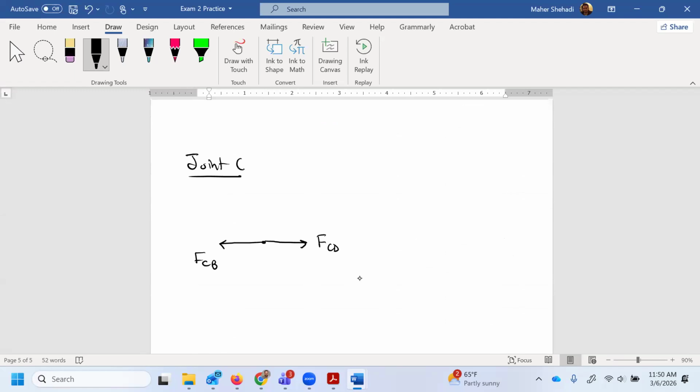I have the member that I'm looking for, CJ, and it has a slope of, we already found it, similar, 3, 4, 5, and I have FCH, and I'm gonna remove this one, we already said it's 0 here. FCH with a slope of 3, 4, 5.